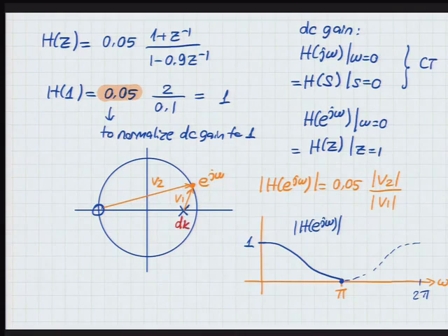Okay, so then how would I modify my transfer function? Does anything change in the numerator? No, we still have a 0 at -1, so the numerator should stay as it is, 1 plus z inverse. Now the denominator is a little more general. Why am I calling it dk? It was dk when we had many poles. Let me see what I used in the notes. Yeah, let's just call it alpha.